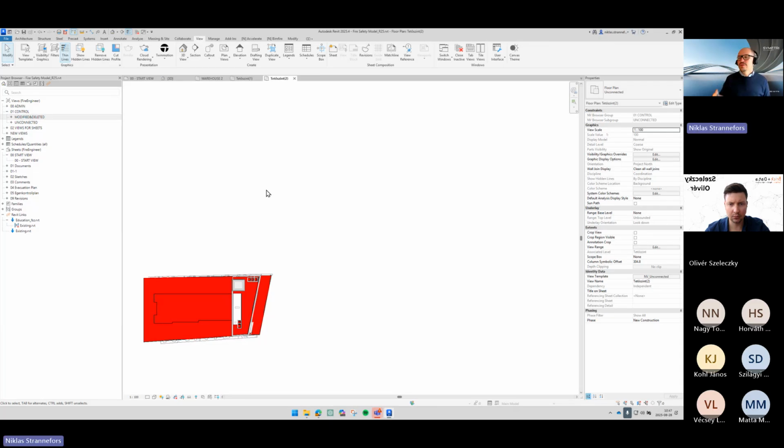And we're going to go through each one of these to see how it looks when we're actually designing. So views for sheets are views that we're going to put on sheets, and that are going to produce our PDF. We still need those PDFs. Modified and deleted is a view with a view template that colorizes the different components in the view based on a parameter called Naviate or NV audit trail status. And it's going to colorize if it's been modified, been deleted, has a type change, whatnot.